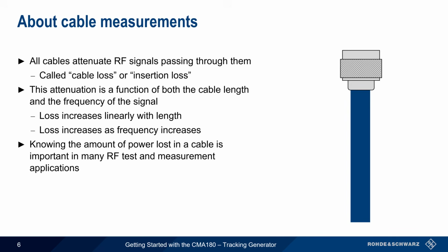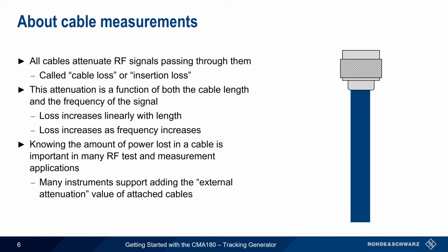Knowing the amount of power lost in a cable is very important in many radio frequency applications, so much so that many instruments support entering the external attenuation caused by cables, so that this loss can be taken into consideration when calculating and displaying results.